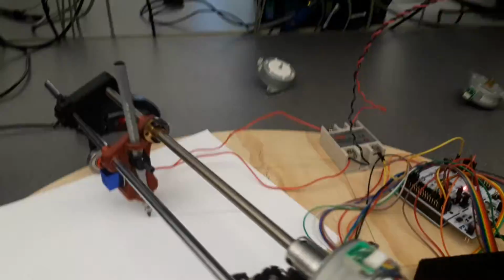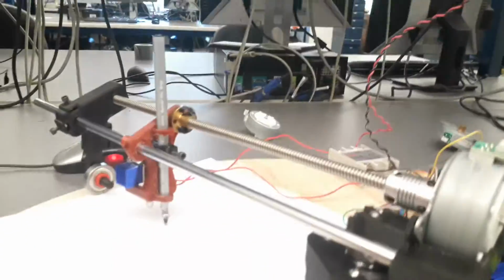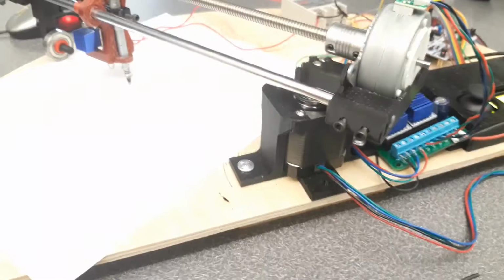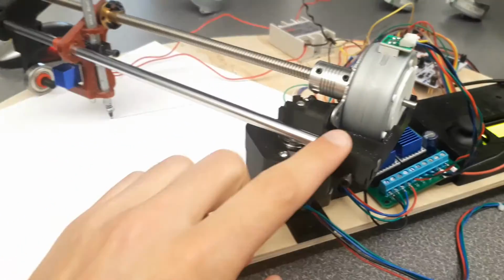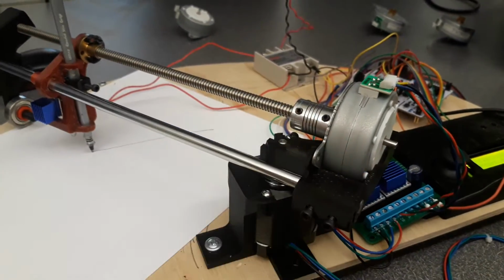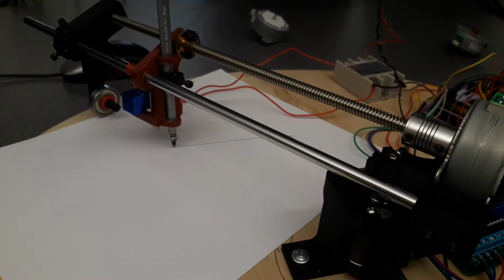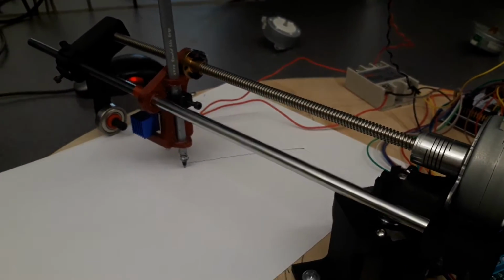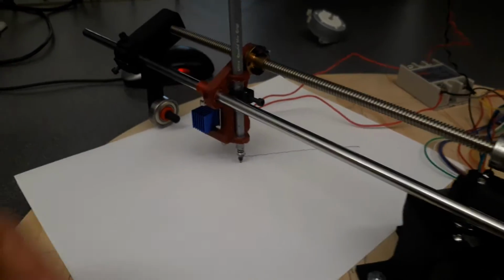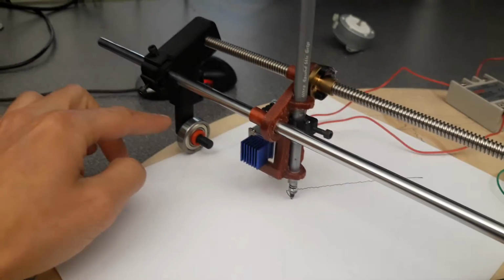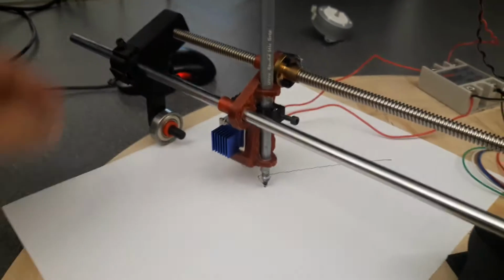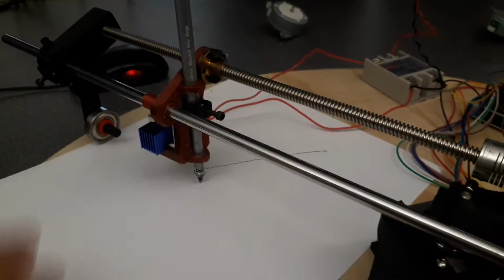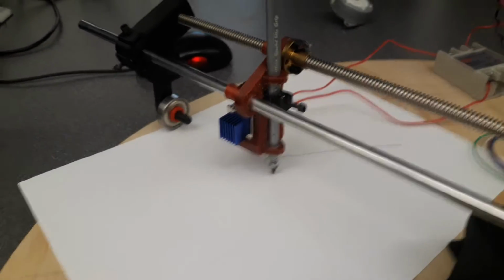I'll take a moment to talk about some of the manufacturing of this. A majority of these components are all 3D printed. So we have all these supports and motor holders to hold the motor. Those are all 3D printed materials. I have a variety of set screws on here just to allow for adjustability. Maybe you want to change the height of this roller bearing to help angle it correctly for the pen to make proper contact with the paper.